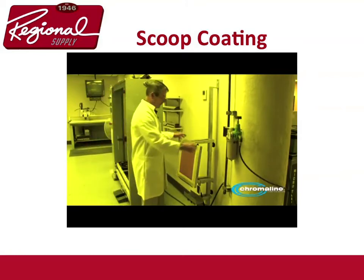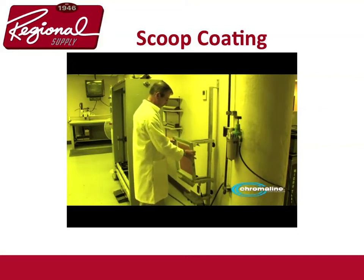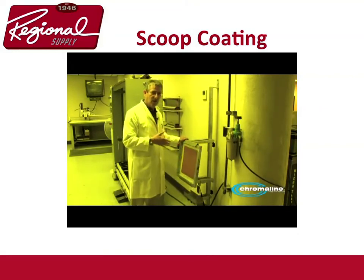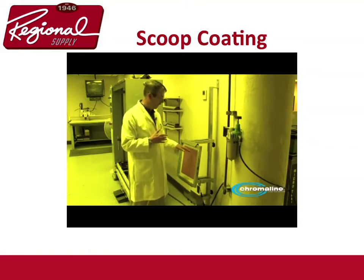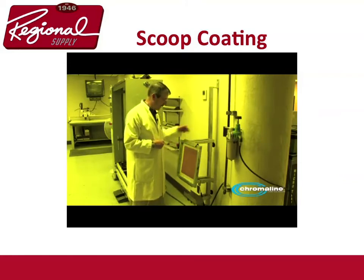The next step is to turn it around. Now we at Chromaline don't care how you coat your screen as long as your last pass is always on the squeegee side. The reason you want to do that is because the scoop coater pushes the emulsion through the screen. That's important. So that's one coat.